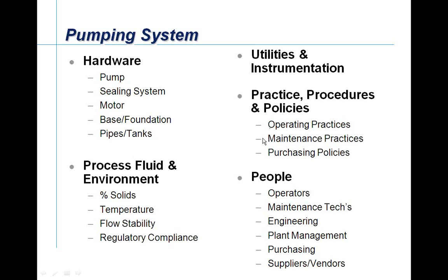These two here, the operating practices and maintenance practices, are very critical in how people are operating these pumps. An example would be one of the procedures or policies you should have: when you start a pump, what are the proper ways to start a pump? What are the proper ways to shut down a pump? There are differences in how you should do it. And then most important of all, you have the people: the operators, the maintenance techs, engineering, plant management, purchasing, suppliers, and vendors.